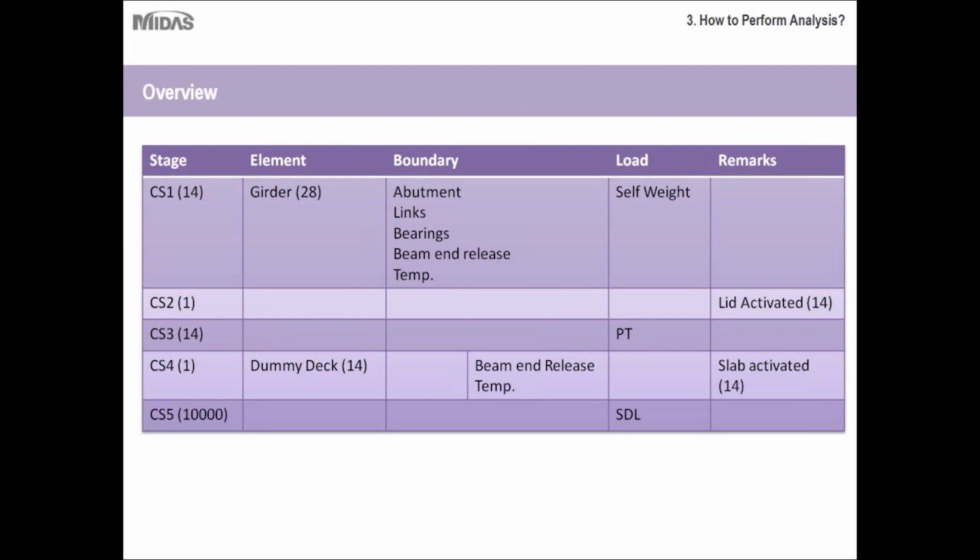I have not modeled the weight of wet concrete on the structure. I agree this is important. So you can consider the weight of wet concrete applied in this stage. And in the following stage, we have activated the members that represent the deck on top of the girders.